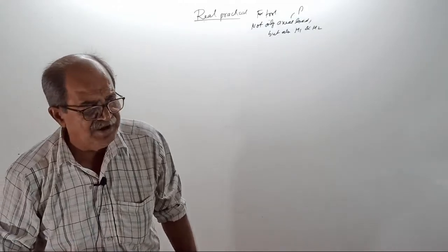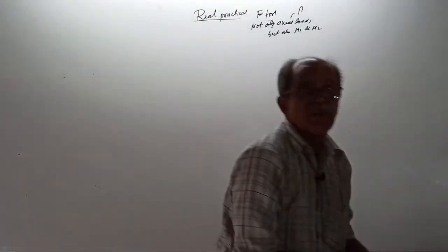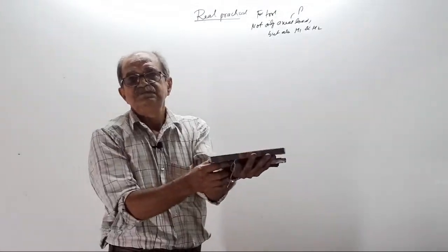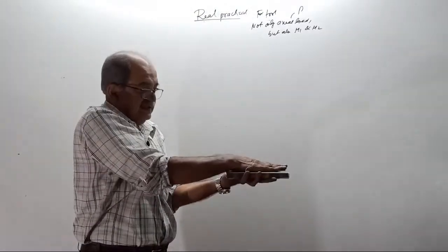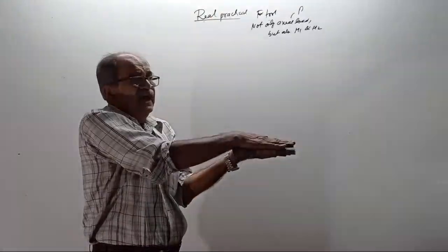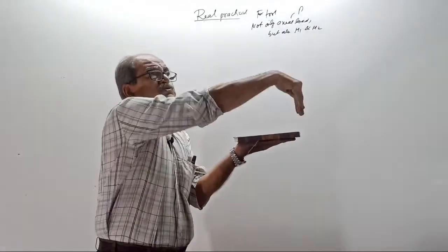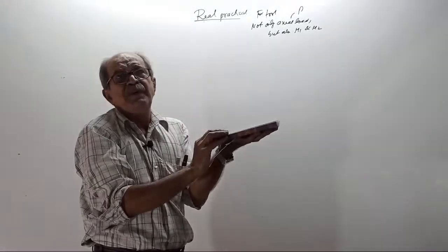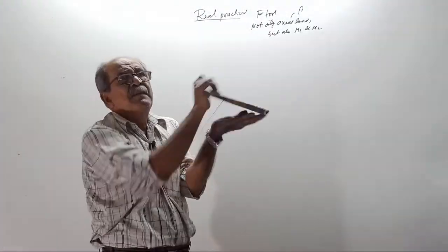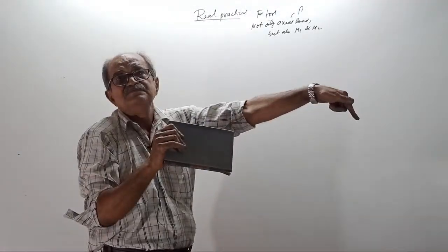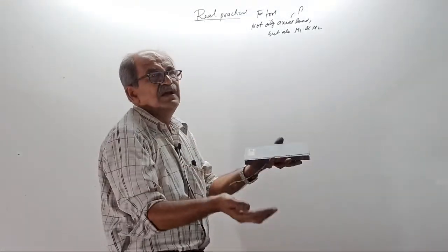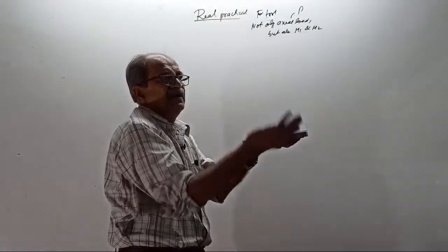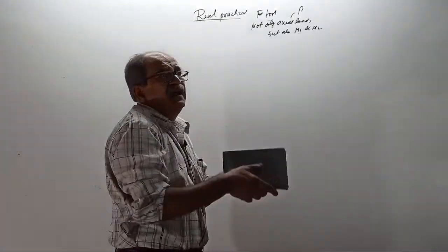See, only once I will tell. Footing. See, footing. You should make a note. Axial load. Axial load will give compression. This way, moment or couple. It is not called bending moment. See, this way. It will try to lift this side, but push that side. One couple I will take this way. Anything will do. Either this way or this way. Design is same. Direction not required. I will take this way. Okay. It will push this side, lift this side.